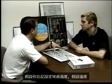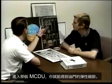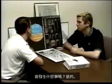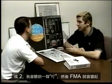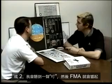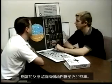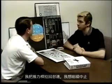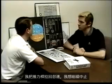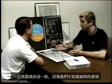Let's say you forgot to set that flex temperature or that assumed temperature into the MCDU. You get the throttles to the flex detent. Would anything occur? Yeah, after about a second or two, I'm going to hear a single ding, and there's going to be an FMA up there that says FLEX TEMP NOT SET. Appropriate response would be to shove both throttles up to the TOGA detent. However, if I didn't recognize that and I was wondering what was going on, I pulled the thrust levers back to idle, I'd want to continue with the abort, even once I realized it, because we don't know the performance at the point that we're at on the runway.